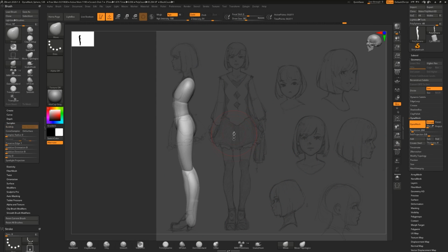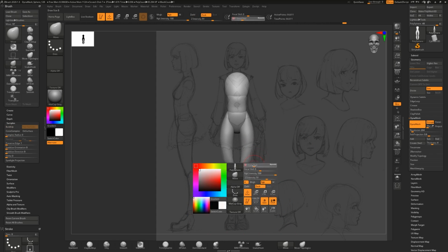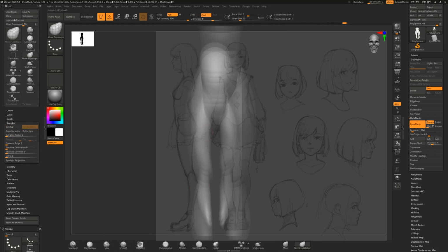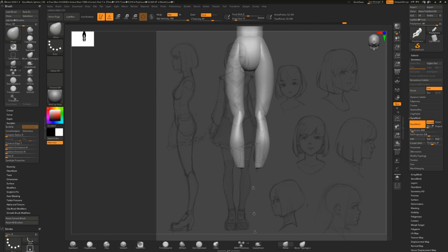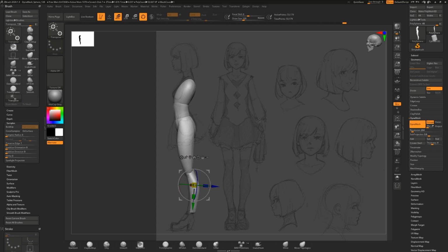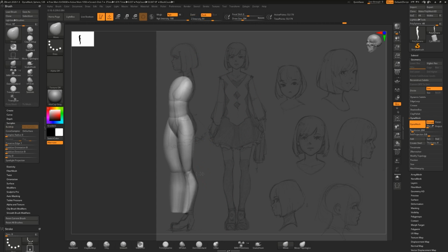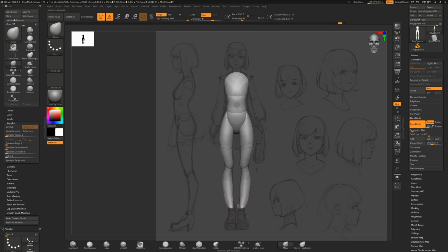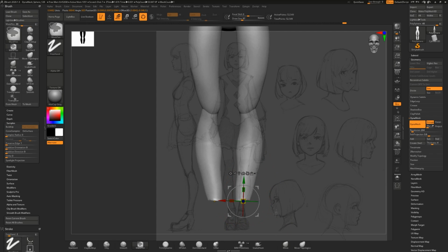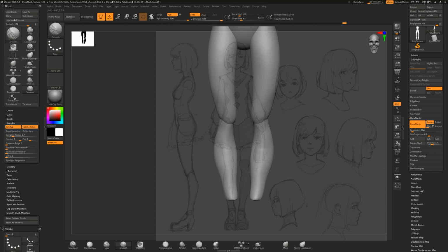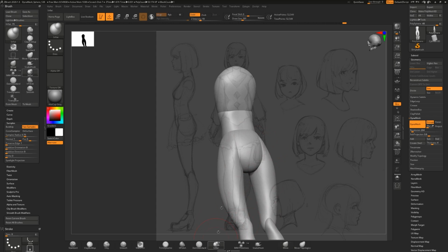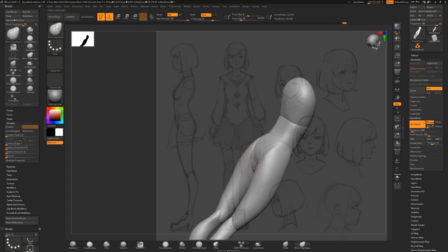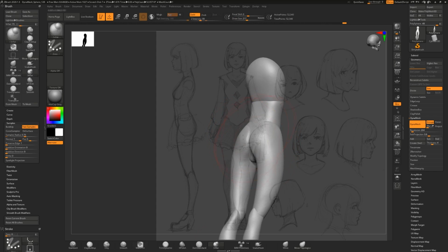And that will require you sometimes to recalculate the density, the geometry, the mesh. And the best way to do that, in my opinion, is to go to the polygroups panel, press Auto Groups to assign one polygroup to each loose part, and then to use Dynamesh, but make sure that you activate that little Groups button that should be available next to the Dynamesh tool.